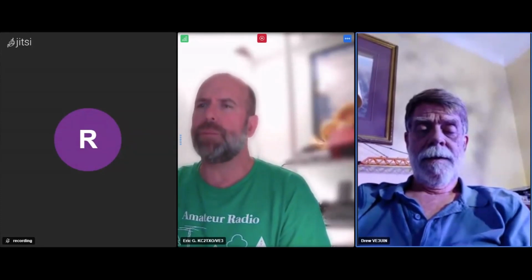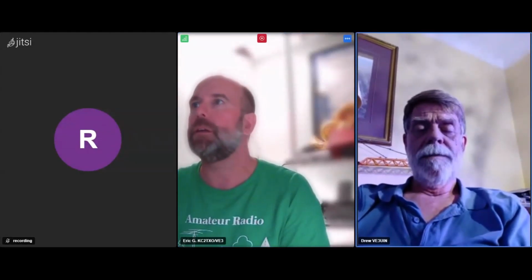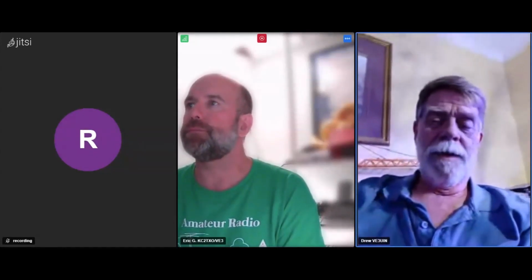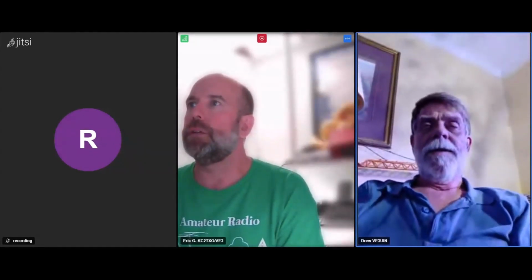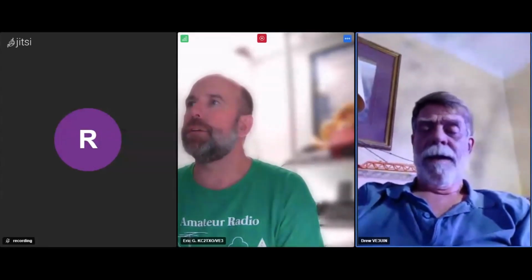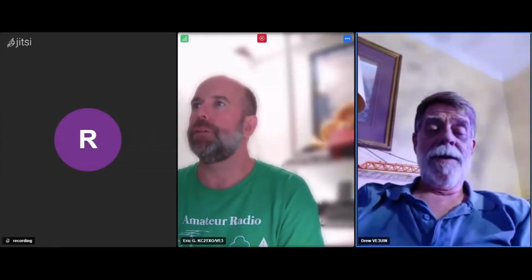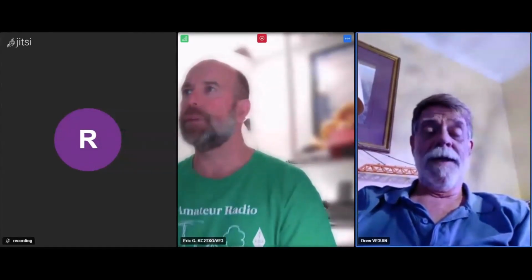Yeah, there is a calibration thing that you can go through, I think it's intended to compensate for situations, like an open, short, and some standard process. So it's like a VNA. Yeah, this thing's got the 50 ohm load and then the open and the short. See, I was just thinking if you just take an ordinary resistor, like a 50 and a 200 and a 100, and put it across the antenna leads on the analyzer, see what it comes up with.